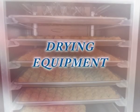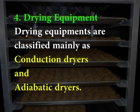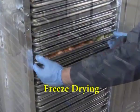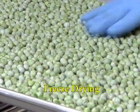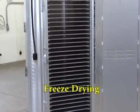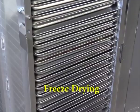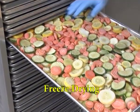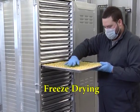Let us discuss drying equipment. Drying equipments are classified mainly as conduction type and adiabatic dryers. Freeze drying is a conduction dryer and state-of-art technology. It involves freezing of the sample and removal of the moisture by sublimation under high vacuum by heat transfer.